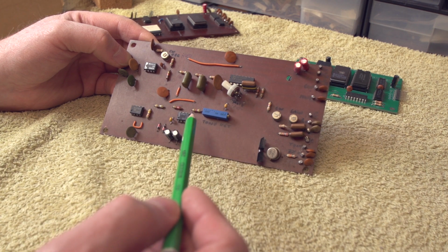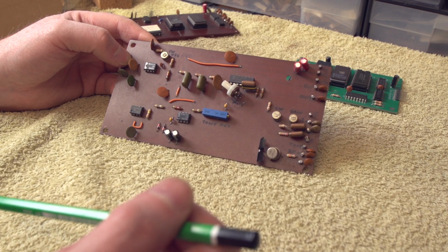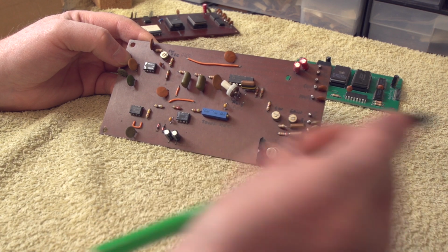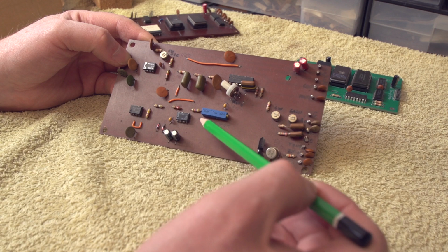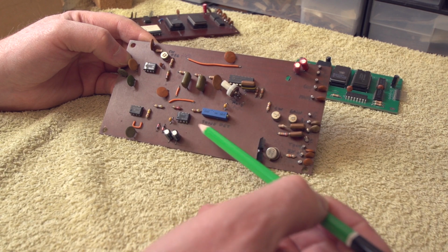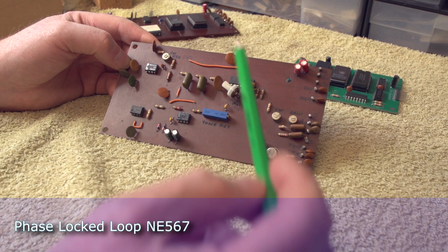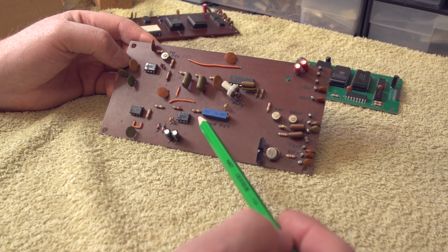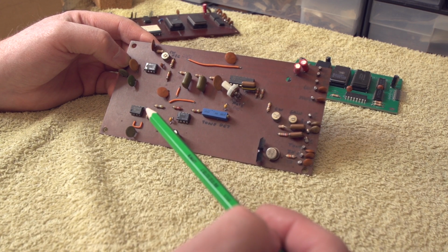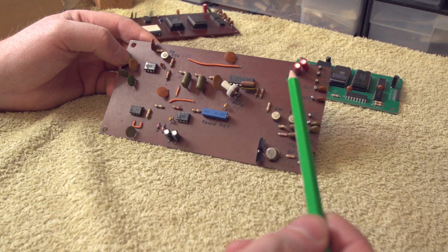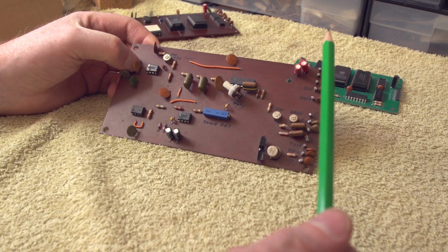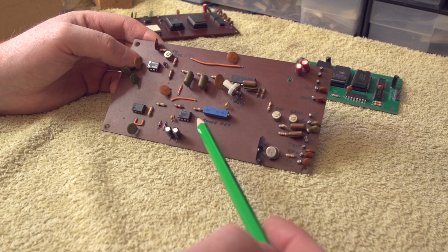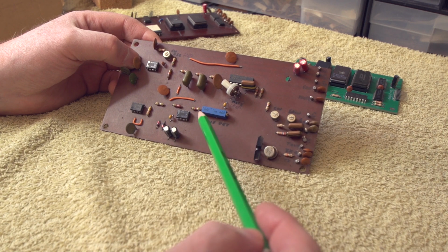Now, the tone burst originally was a frequency of 1750 hertz, 1.75 kilohertz if you like. And that was the injected tone that the transmitter would send. The receiver at this end would pick it up, and this phase-locked loop would detect whether that tone was present or not present. So that's the old way that it used to be done. Now, this system's not been in use for some years now. All of the repeaters, certainly in the United Kingdom, and I'm sure in most other countries by now, have done away with this system. They now do not use the tone burst system of 1750 hertz to activate the repeater.